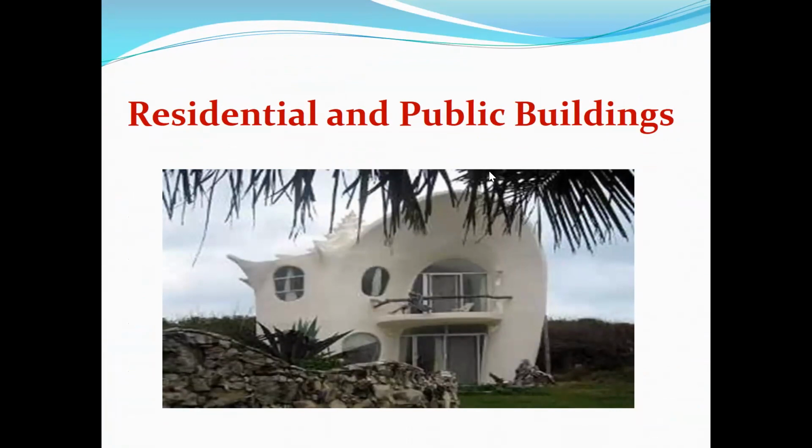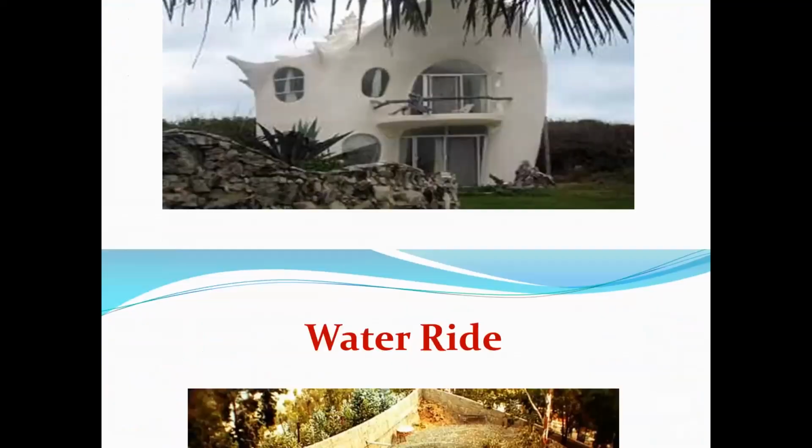It's not necessary that the whole building is made of ferrocement structures, but maybe some part is made of traditional concrete and some part where you need to give a compound curve like that. So then you have to make a shape like this. You can use this compound curve shape, which is a very thin wall. Okay, so that you can make with the help of ferrocement technology.